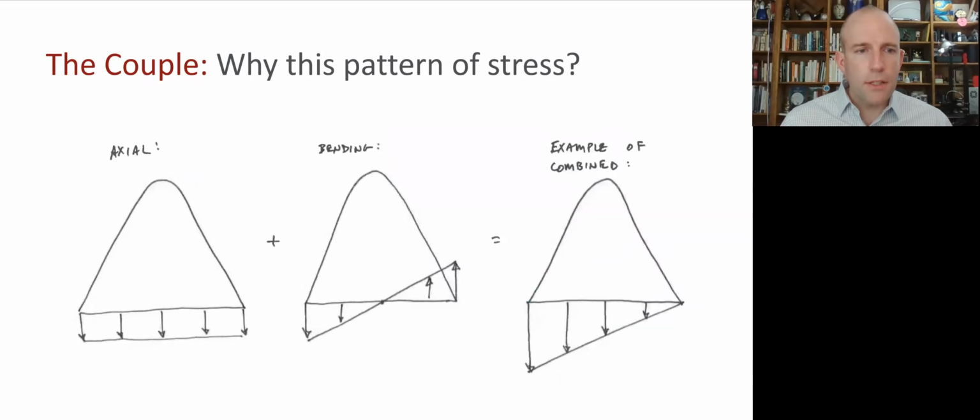And what's happening is, if you think about those diagrams you saw in solid mechanics, you've got this axial pattern of stress, which is nice and even across the cross section. And you've got this bending pattern, which strongly varies across the cross section. And then you add them together. And on this side, we've got tension adding to tension, and we get more tension, so bigger stress. On this side, we have tension that's adding to compression, and they cancel each other out, and we're getting low stress.